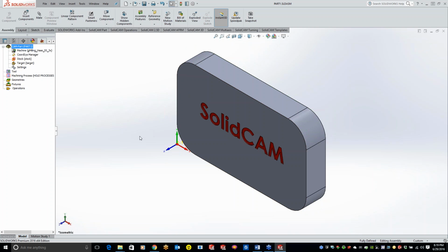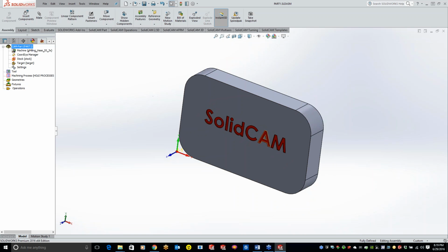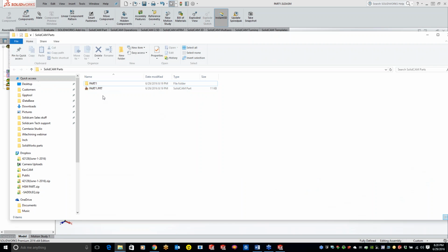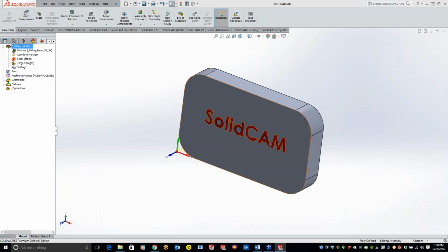So with uncompressed, you guys are going to see a lot more information in there of what's going on. If you guys are running on a server of any kind, or where you are saving files over a network or a shared center or anything, I recommend not using this, because when you click the Save and Calculate to do toolpath, you'll see much slower save and calculate times with the uncompressed, because what it's basically doing is working on the folder as we speak right here. So let me just minimize that for a second.